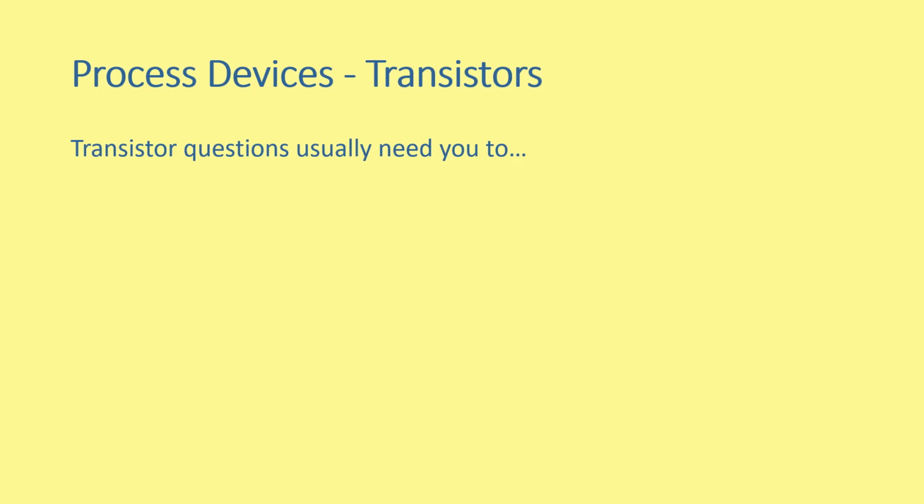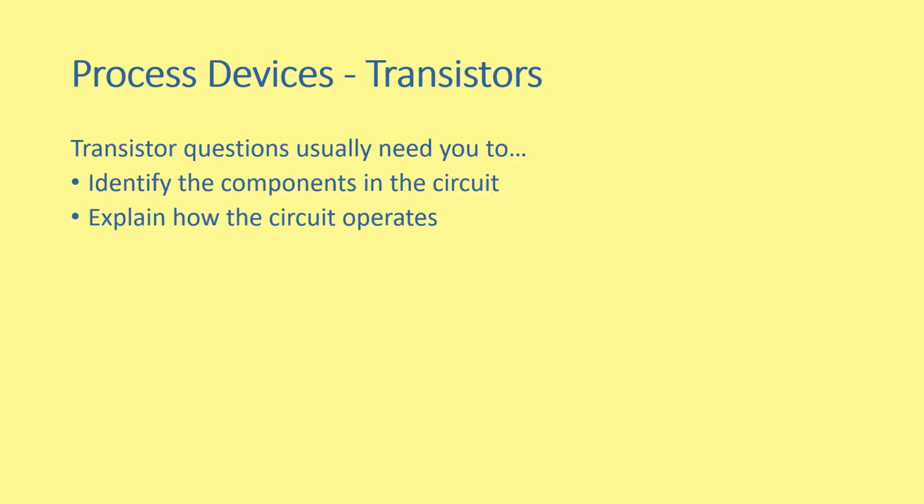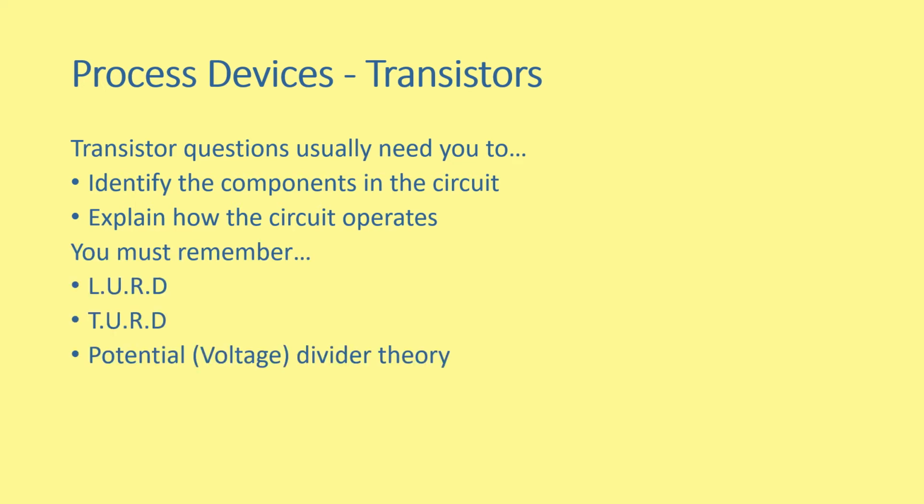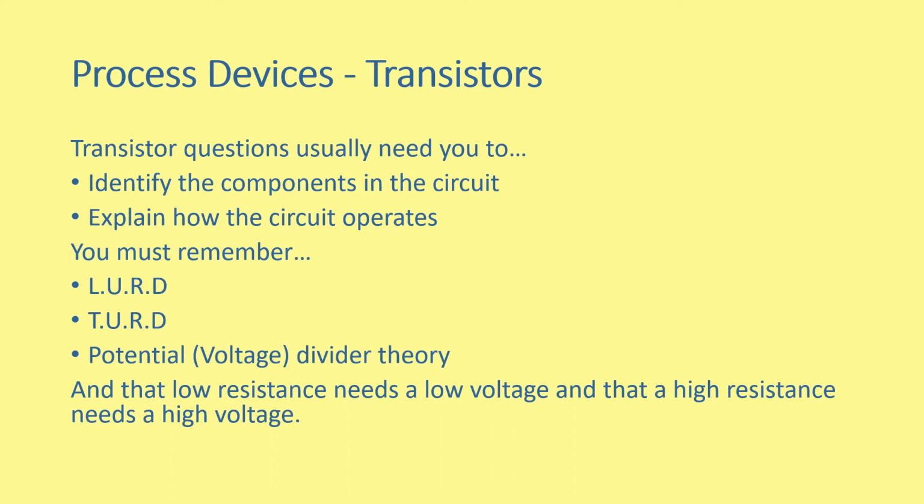Transistor questions usually need you to identify the components in the circuit and explain how the circuit operates. You must remember LURD, so light up, resistance down, TURD, so temperature up, resistance down, and potential divider theory. And that low resistance needs a low voltage, and that a high resistance needs a high voltage.